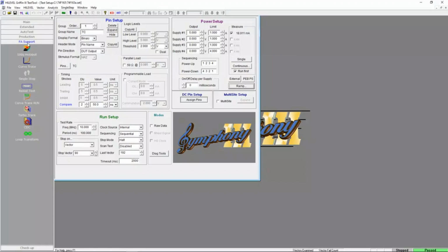Liquid crystal IDDQ hotspot, traditionally used as a failure analysis tool, employs the rampability of the DUT power supplies to apply a precision-tuned pulse on VCC pins while the surface of the exposed die is observed. Its name was inspired by liquid crystal film used to observe temperature gradients on DUT die. Nowadays, other thermal imaging techniques are used, but the principle remains the same.